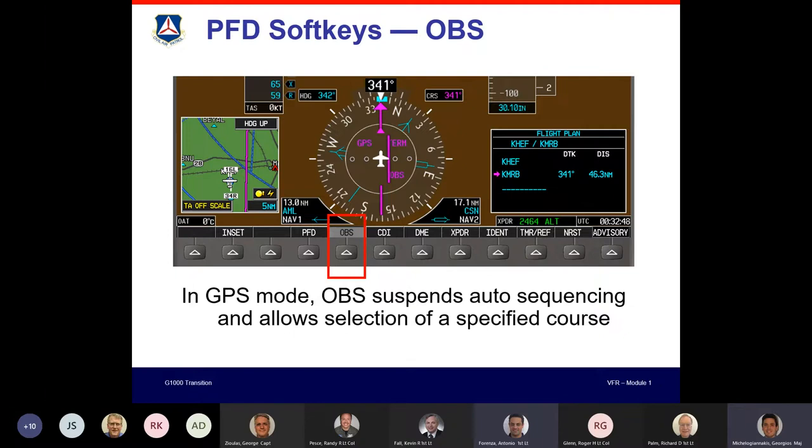But if you have that case happen, I'm not entirely sure, but I think you can still tune the frequency on, for example, NAV2. You won't get any course guidance, but if it's in the database, it might work out. I think that's the key. It's GPS derived, so it needs to be in the database.